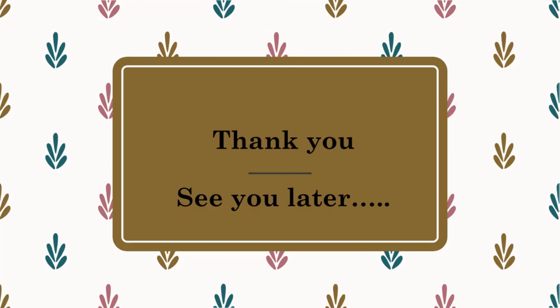Okay, that's all for this topic. The first topic, which is under soil compositions, we already discussed everything. I already discussed with you all the basic equations in geotechnical parameters. Okay, basic equations for index parameters, which are void ratio, porosity, degree of saturation, and void content, where all the basic equations are based on volume. And you also have water content, which is based on weight, and you also have unit weight, also known as density, and specific gravity, achieved from the relationship between volume and weight.